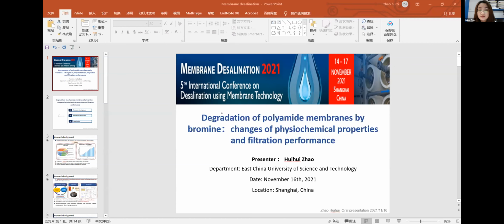And bromination disinfection is also commonly used in seawater desalination. That is chlorination with bromide ions. The bromide ions can be oxidized to form hypobromous acid, and that is also the common bromination disinfection. And as for the risk of operation,